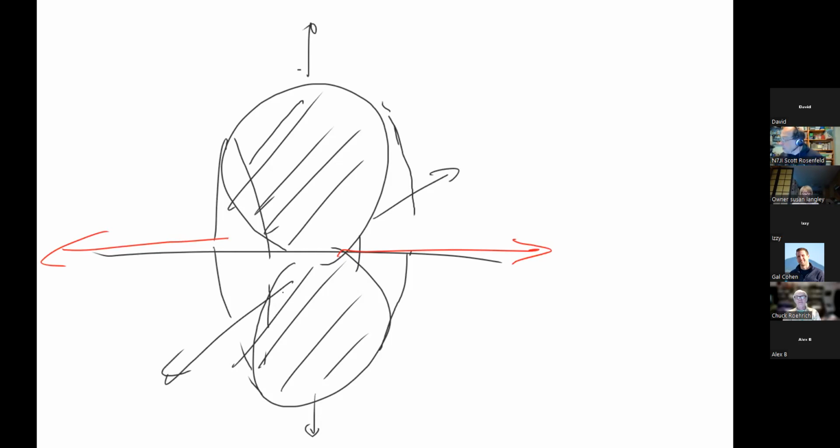And if you rotate it, what happens to the donut? It rotates also. It rotates, so you have a directional antenna. Now, what's the only problem with this antenna? Where's some of your energy going? Straight up into the sky. And some of your energy is going to the ground. Straight down into the ground. That doesn't really do you a lot of good.